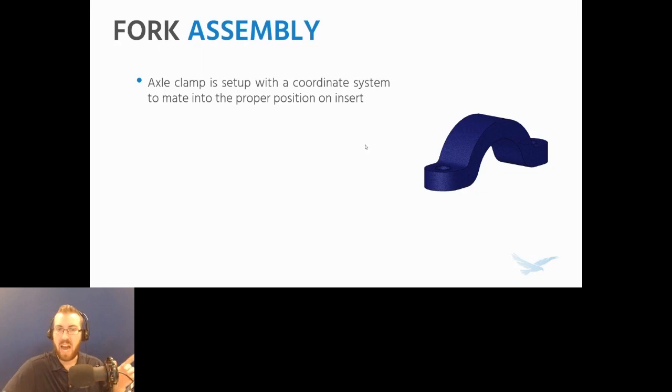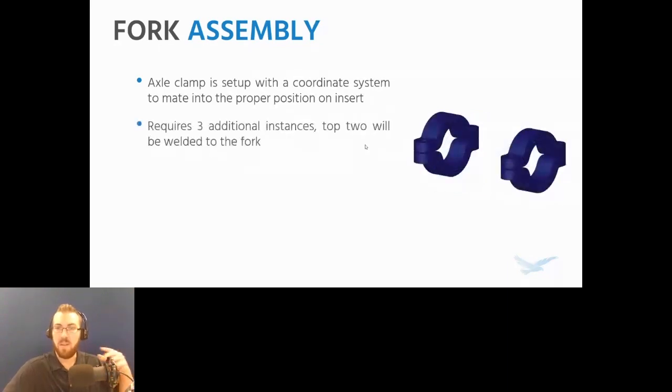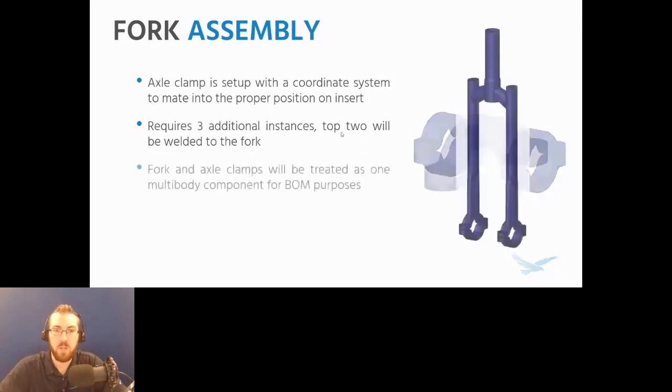We're starting off with this axle clamp. The axle clamp needs to be mirrored about a right plane and a top plane at the same time, ideally, right? This is a situation where we have two planes of symmetry, and in previous years, we couldn't do anything with that other than create two separate mirror features and make it work. That's more information to manage. Now we can do this all in one go with the new secondary plane option for mirror features.